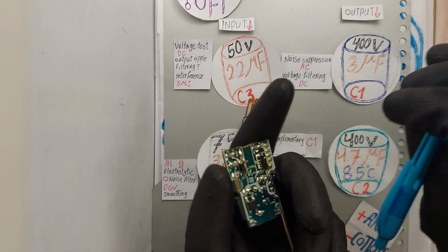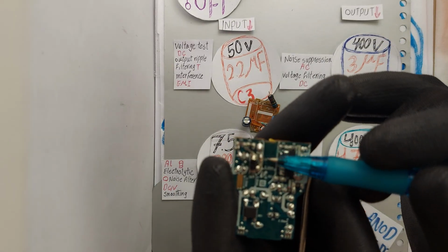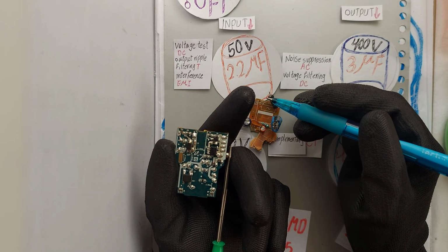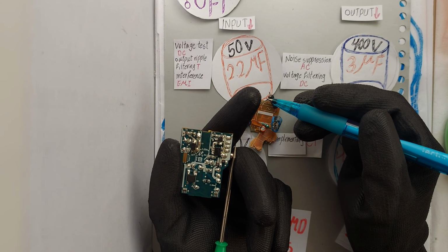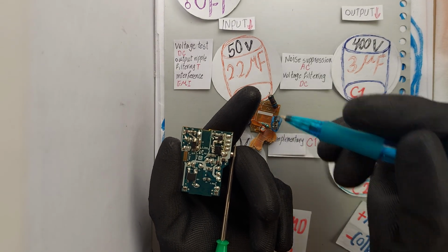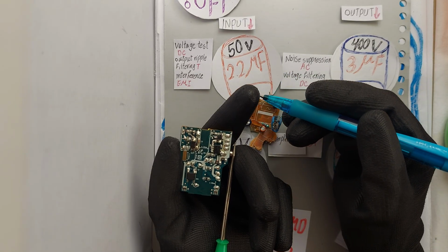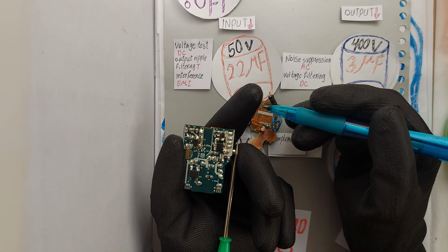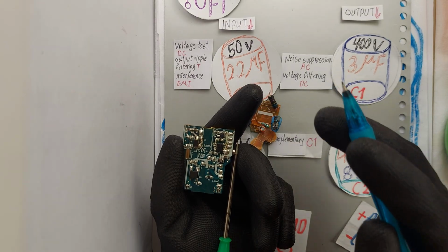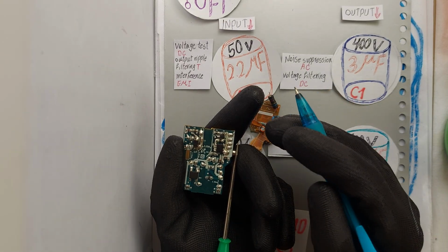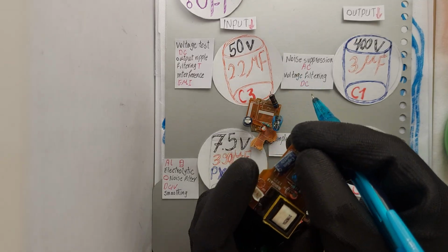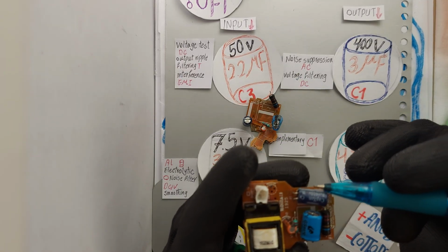Capacitor 5 on the back of the board, as you can see right here. The assembly capacitor on the back of the board acts as an additional filter for high-frequency noise. Due to its small size and surface mount design, it's used in modern circuits to optimize output performance. It complements C4's filtration. So, you might wonder why in the schematic C1 and C2 are shown as rectangular,